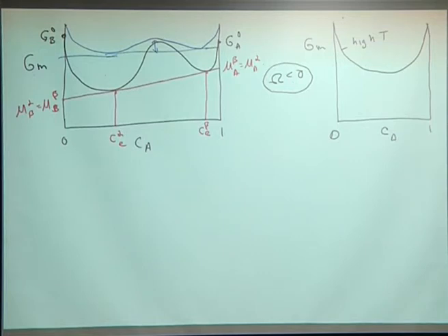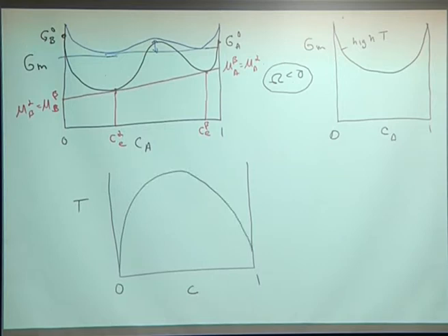So you can plot a phase diagram from this, and you just basically plot the locuses of those two points as a function of temperature, and it looks like this. You'll be seeing a lot of this during the course, and these are what I'm calling alpha and beta. And in the middle, you have a mixture of alpha plus beta. Okay, questions? Comments?